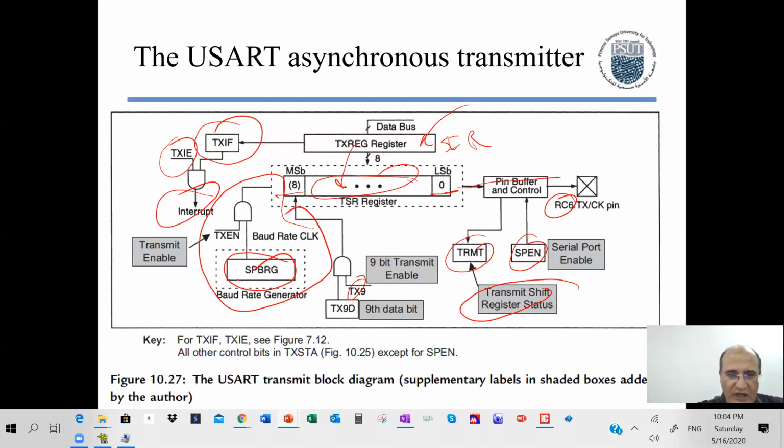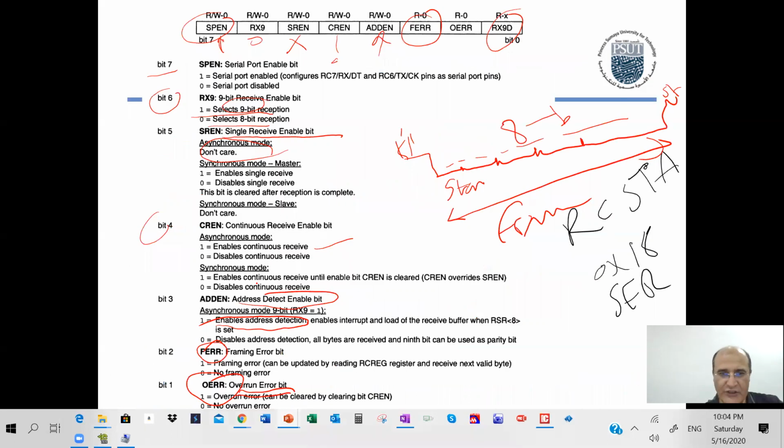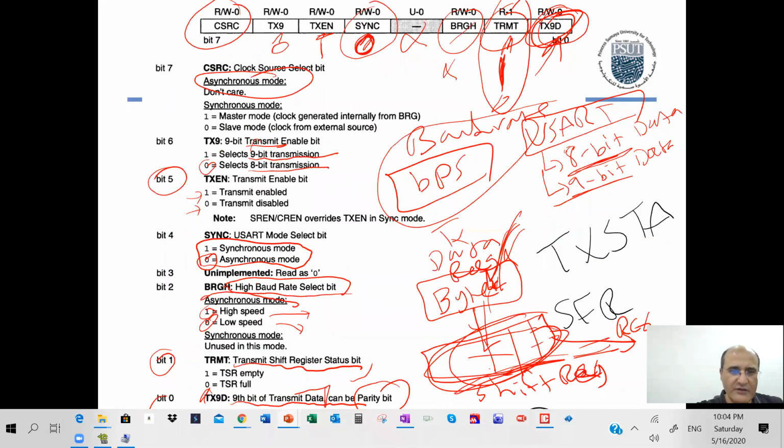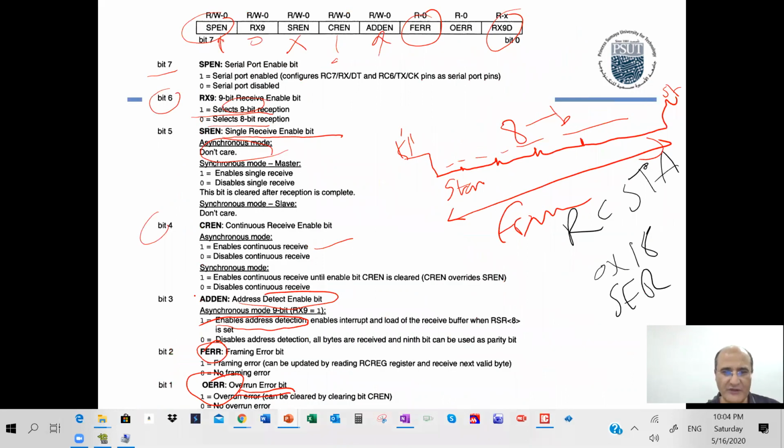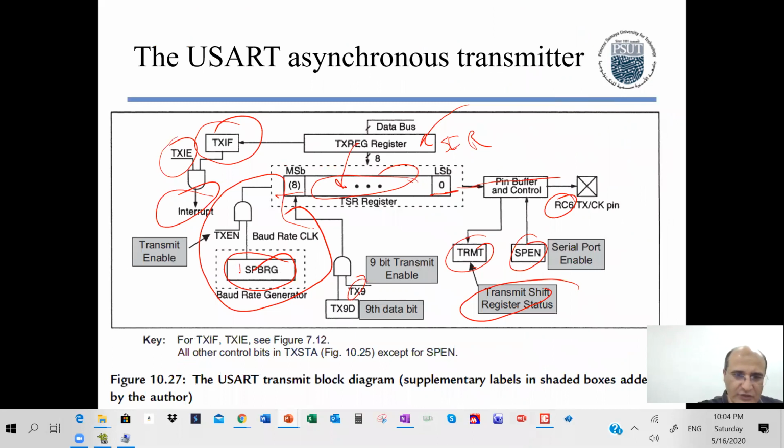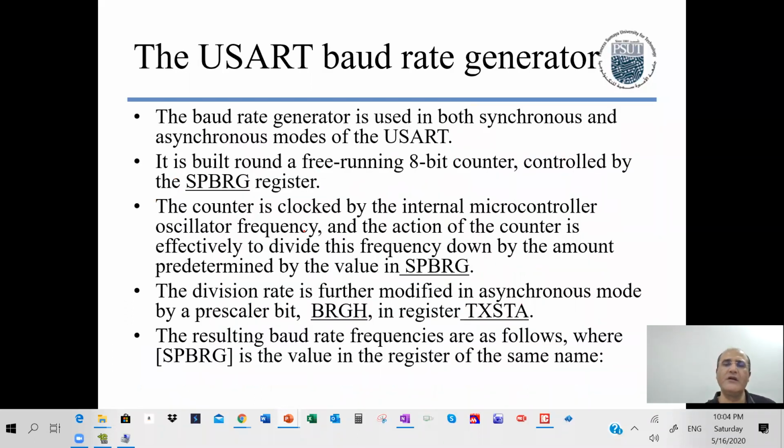This is the bit we talked about to here, that chooses the formula that will compute the baud rate. So there is a register. We need to write a value in it to compute the baud rate. I'll come to it. For you as an embedded system programmer, all you need to do is be able to write to this register. It will shift everything, enable everything. It will be easier when we write the code.